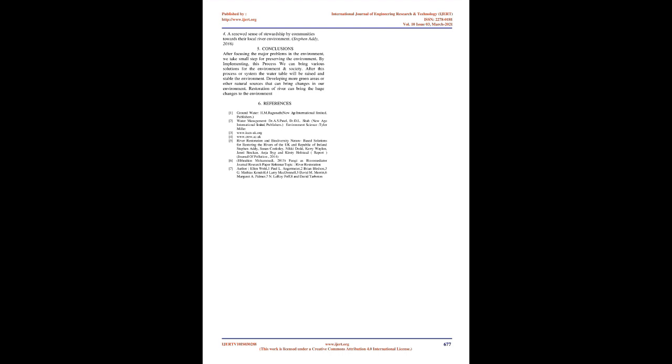3. Principles of river restoration. The six key principles to guide effective river restoration are: improve overall ecosystem integrity and biodiversity, rather than focusing on the status of single species, by using process-based techniques such as floodplain reconnection. Engage with the interests and motivations of different stakeholder groups as early as possible. Discuss objectives, and identify opportunities and barriers, before planning activities.